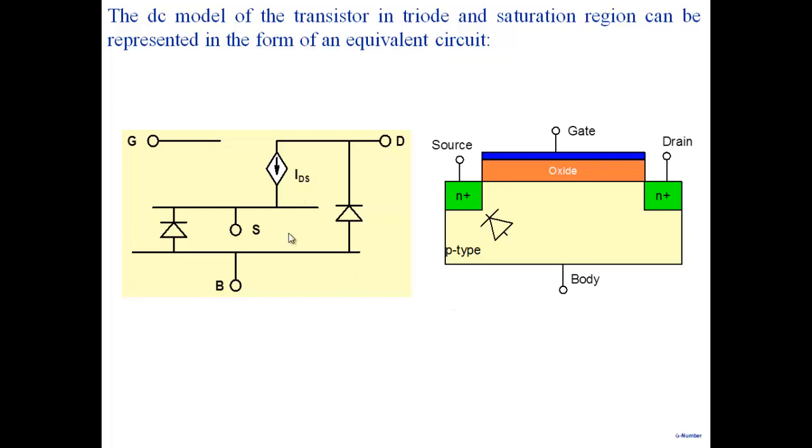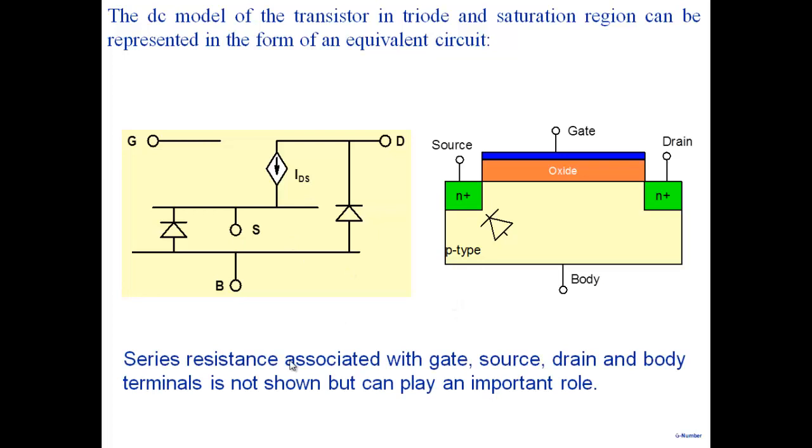Now, of course, each one of these models is simple. As I said, there are resistances. For example, in the simple picture, I have a contact here at the source, and from the source, I have to reach the channel. Right? And you go from the source to the channel going via N plus region here. Now, N plus has a certain amount of resistance. And between the metal contact that you put on top of N plus, there is a little bit of voltage drop there as well.